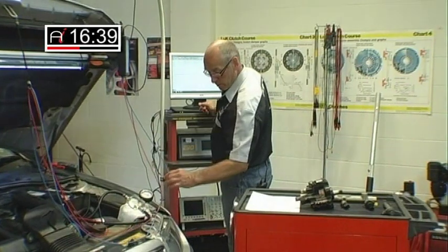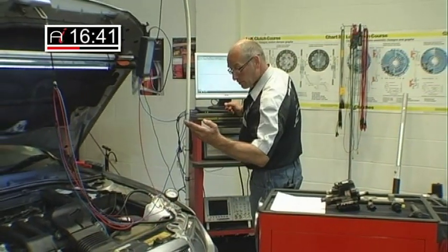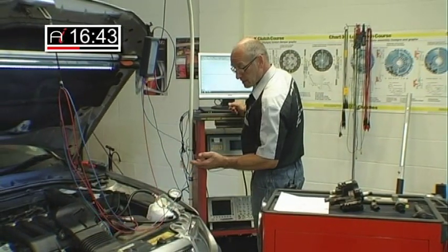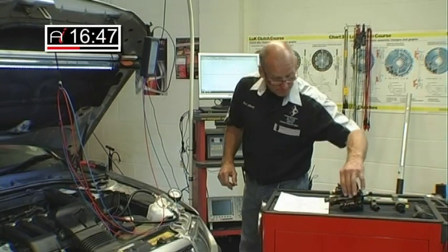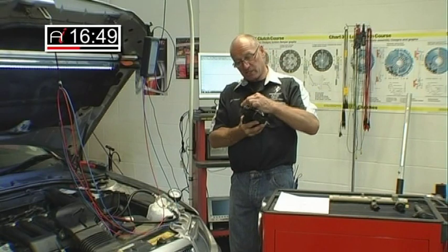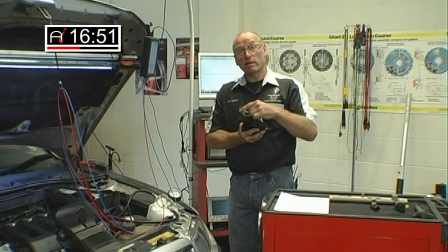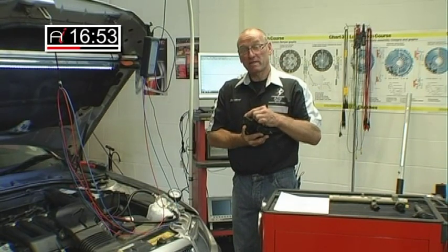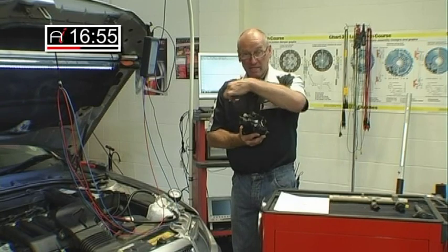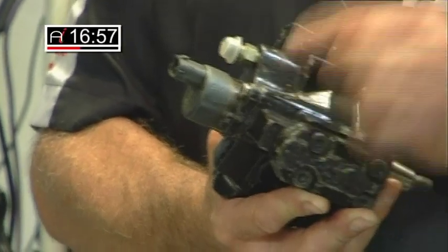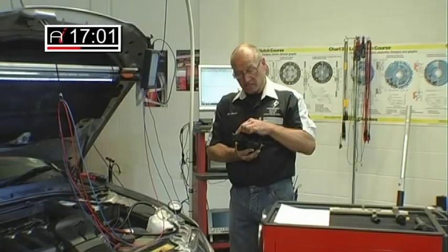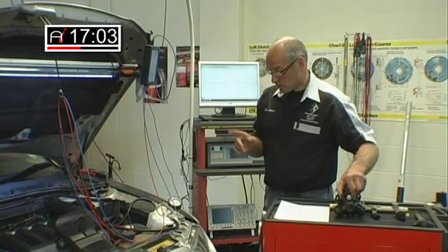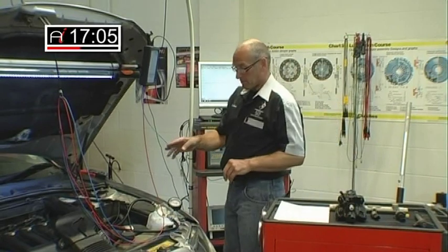The first channel, we'll check where we're connected. The blue channel is connected to the DRV. So my blue probe is connected to the control circuit. This is a ground control device, which means it's ground switched on. On means higher pressure. So the higher the duty, the more the pressure. I'm monitoring that duty with the scope on channel 1.